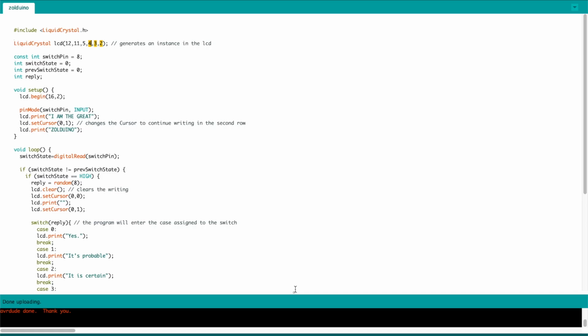It's an option that comes down to design in more complex circuits, timing versus available pins, etc. And it doesn't really make a difference to the Arduino as long as the wiring and the code are consistent. Basically, does the Arduino use 1 or 2 clock cycles to push each character to the display? That's what we're really asking. In this case, we're only using 1 clock cycle per piece, thus we can have a 4-bit buffer.